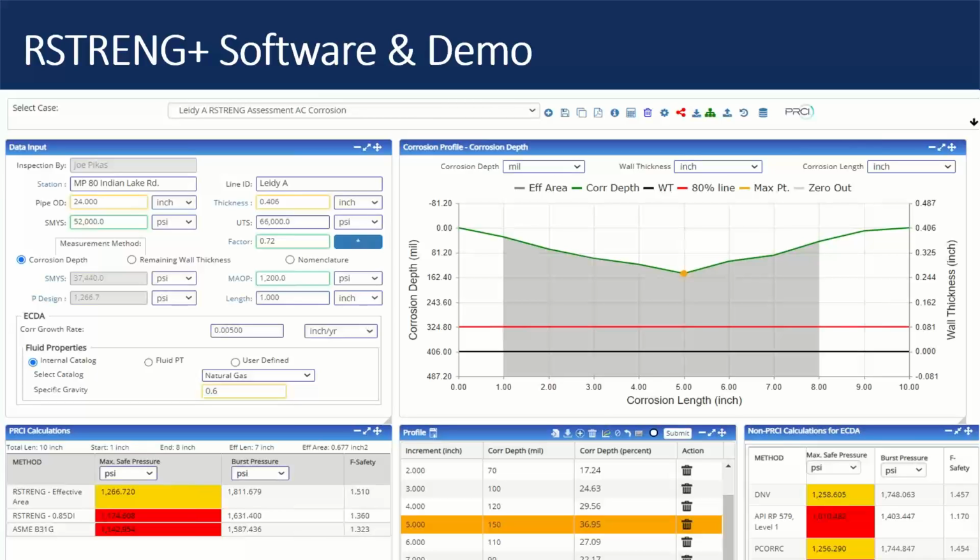And you have to remember the MFL tools are still MFL tools. They have their inconsistencies, as far as wheel counts, even though they have multiple counters, and also how MFL reacts to different pitting, particularly the aspect ratio of pitting. And if you look at this aspect ratio, this would be something they call a 3-to-1.